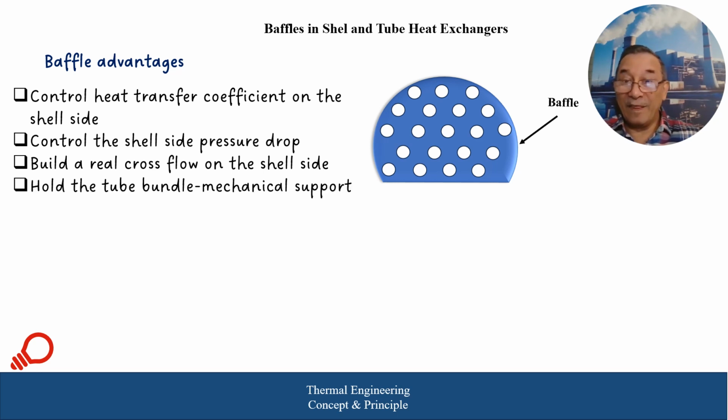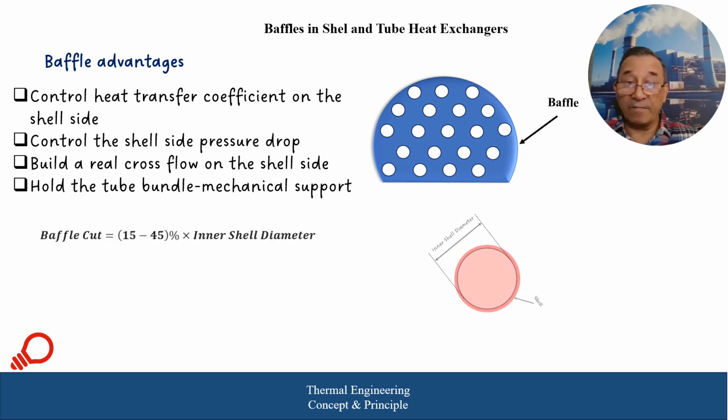Finally, the mechanical advantage of these baffles is to hold and support the tubes as long as you are building a heat exchanger. That means it gives a sort of support for the tubes to stay straight between the tube sheets on both sides of the heat exchanger.